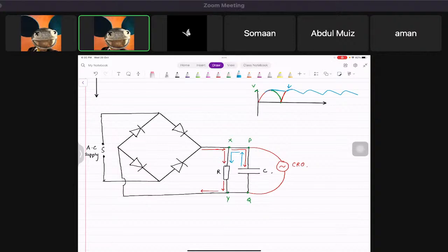So it's sort of giving a filler when the current is not there, when the voltage is dropping. The capacitor is there to fill up that gap or provide the current during that particular time, so that the resistor always has current coming to it, there is no drop of it. Do you guys understand this?